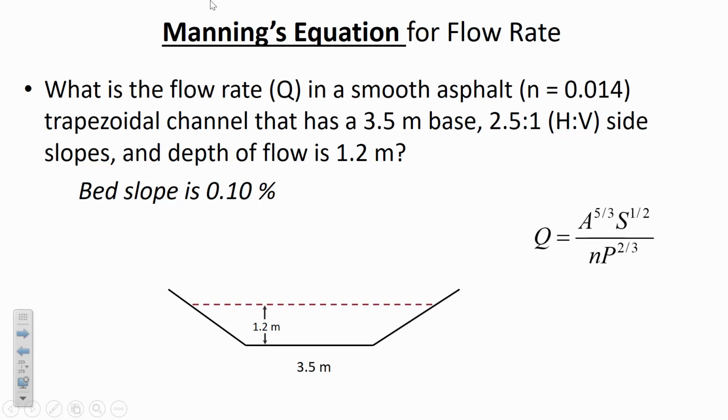So the hydraulic radius is area divided by wetted perimeter. If we combine the area that gives us flow rate rather than flow velocity with the area that's built into the R to the 2/3 power, this is the expression of Manning's equation that I think makes a lot of sense. Last time we focused on solving Manning's equation for flow depth. So that's probably the trickier of the two kinds of calculations that we'll take a look at. Today we're just going to solve for the flow rate.